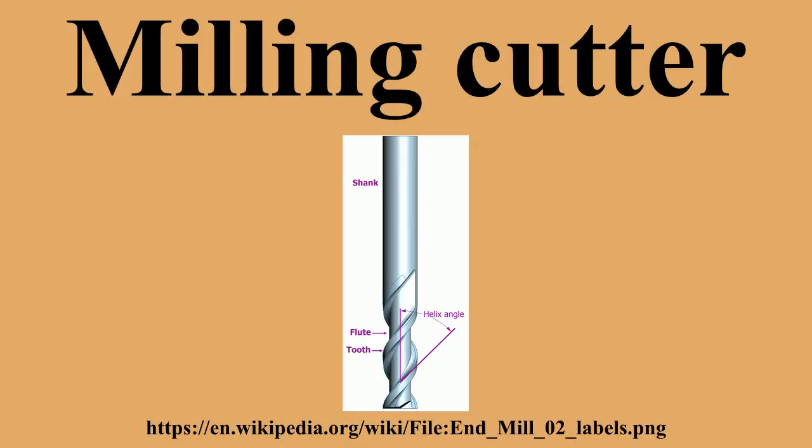Roughing or finishing. Different types of cutter are available for cutting away larger amounts of material, leaving a poor surface finish, or removing a smaller amount of material, but leaving a good surface finish. A roughing cutter may have serrated teeth for breaking the chips of material into smaller pieces. These teeth leave a rough surface behind.